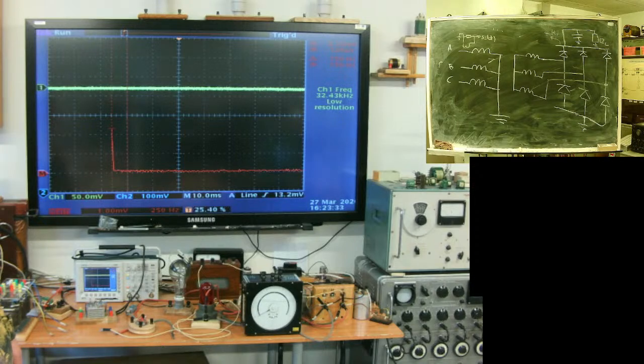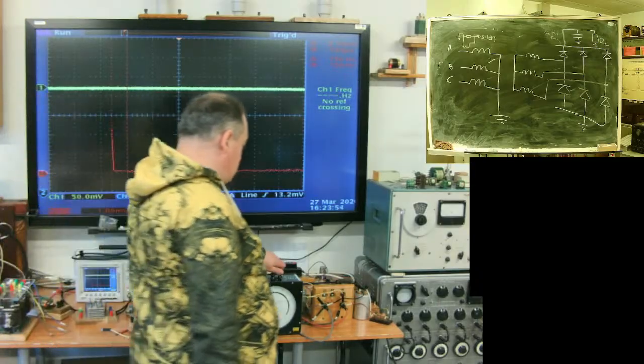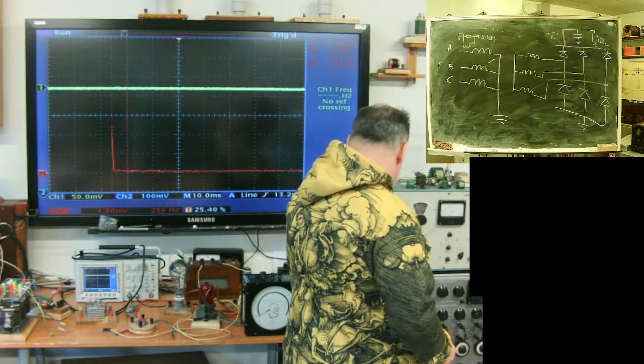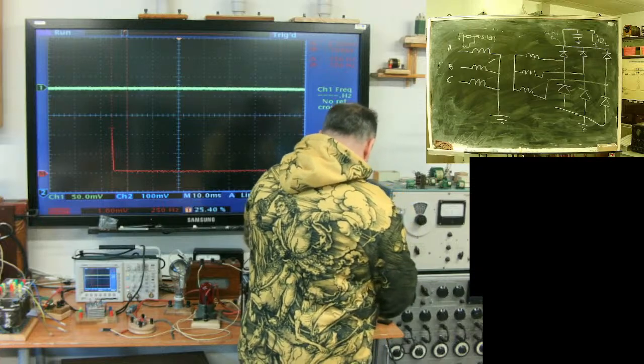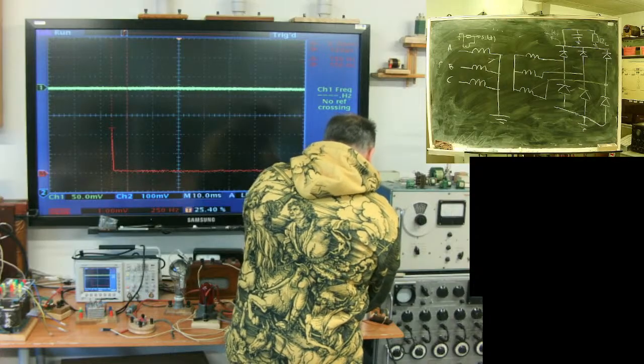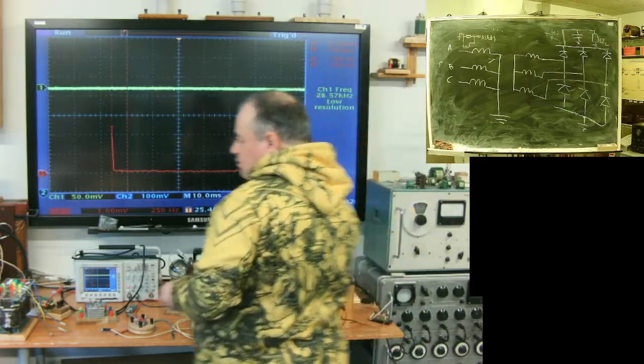In case of single phase loads, even combined in three phase, we see huge amount of third harmonic. In case of larger industrial, there is no way third harmonic can close, so they do not produce third harmonic, they produce fifth. And fifth harmonic does not fall in a neutral. There is no fifth harmonic in neutral.